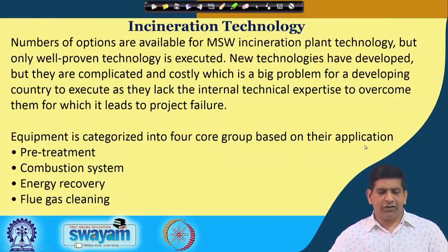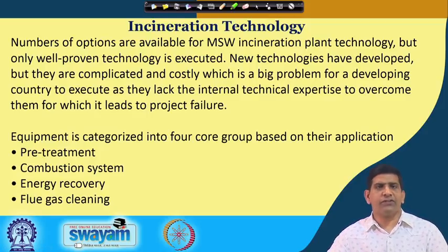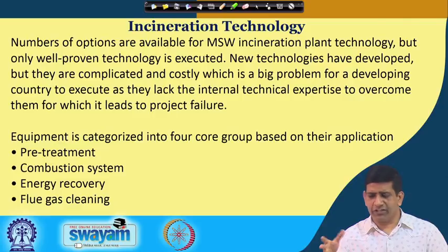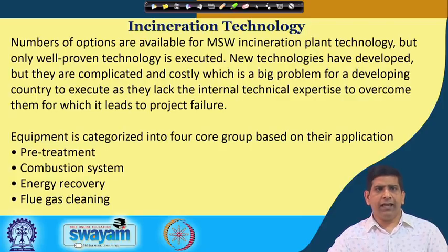As for incineration technology, there are a number of options for municipal solid waste incineration plants, and mass burn is the most common. There are new technologies that have also been developed. Some of them are complicated and costly for a developing country to execute, but the most common is either mass burn or refuse derived fuel. In some cases you may have to do some pre-treatment as well.